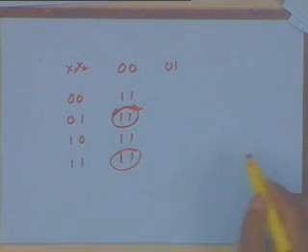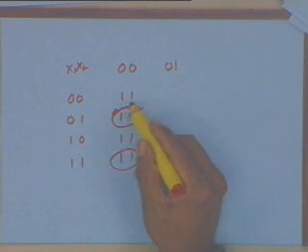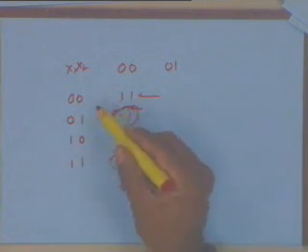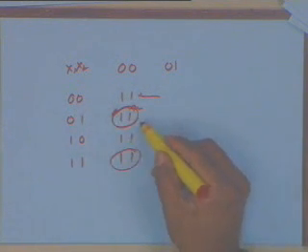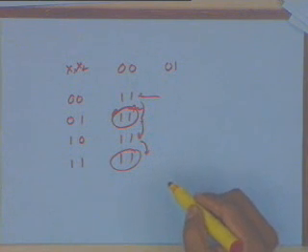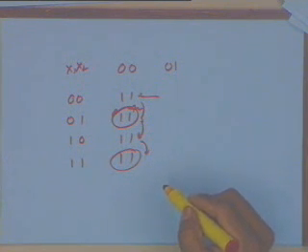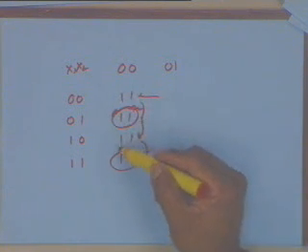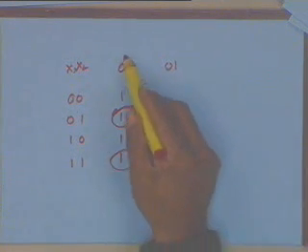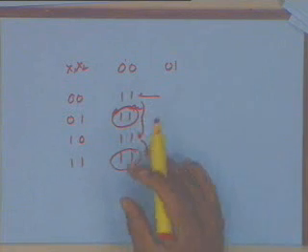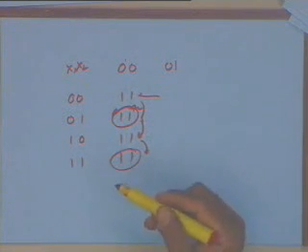So if this particular input changed from this to this, wherever, let's say I want to actually go from anywhere to anywhere. I go, but whichever state I reach, I finally will be directed on to my stable state 1, 1. I can make my secondary state assignments in some manner, so that for this particular input state, there will be a non-critical race that will result. I will make some transitions. We will of course consider a more detailed example of this when it will be clear.